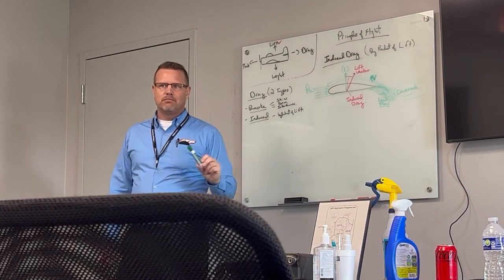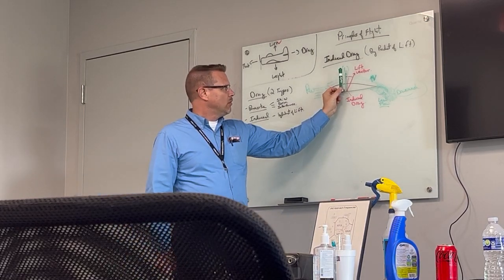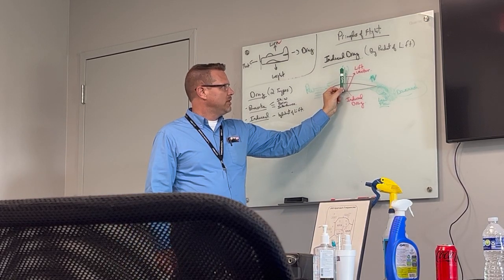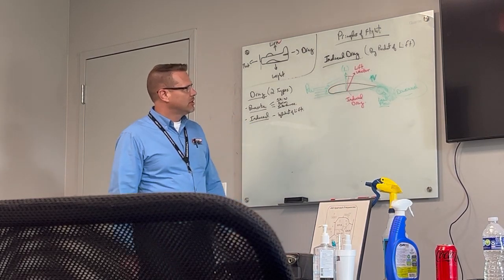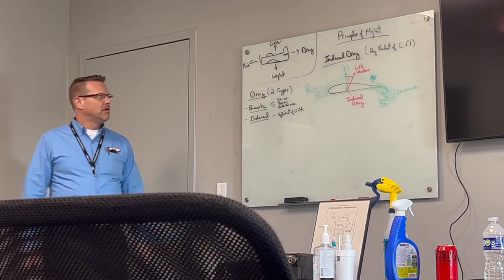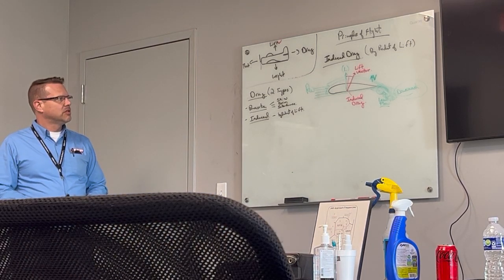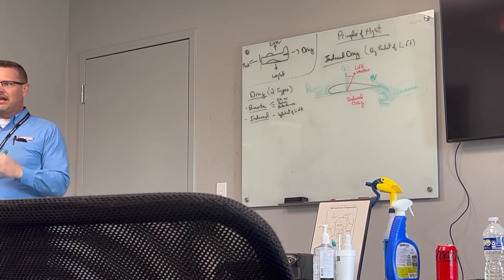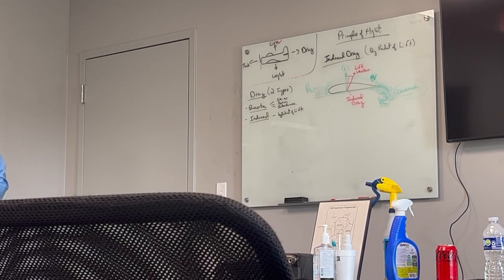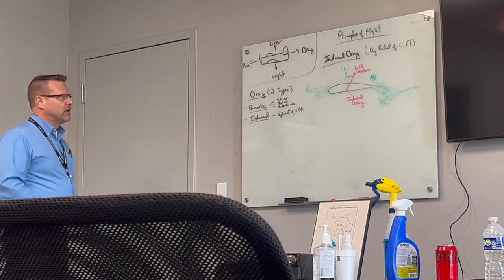The difference between the lift vector where it would be perpendicular to where it gets slightly pulled back is our measurement of what's considered induced drag, and that's the drag that's literally formed by the wing itself. Induced drag is not formed anywhere else but by the wing.